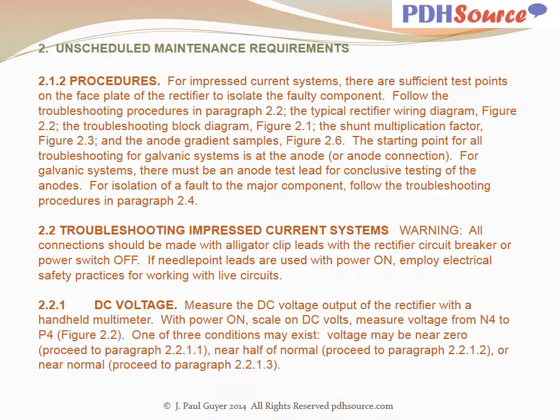Troubleshooting of impressed current systems. First, a warning: all connections should be made with alligator clip leads with the rectifier circuit breaker or power switch off. If needlepoint leads are used with power on, employ electrical safety practices for working with live circuits.